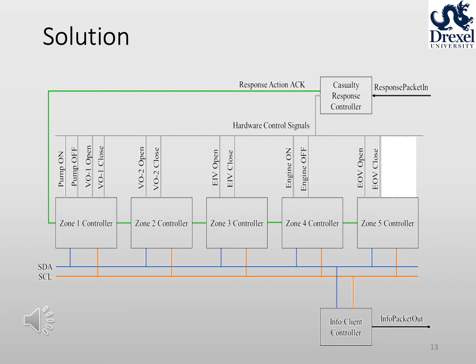To solve the communication issue, the above controller schematic was developed. It prescribes not only the placement and intercommunication of each controller, but also the controls that are to be operated from each. The communication issue was solved via the implemented I2C bus. A separate controller responsible for compiling and sending the system status message to the DAU would poll each controller for an update using this I2C bus. Once the polling routine was completed, the message would be sent to the DAU.